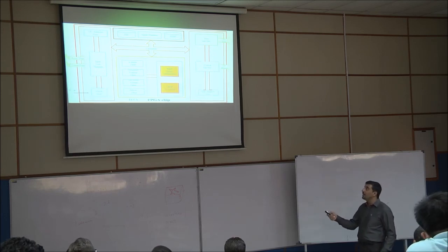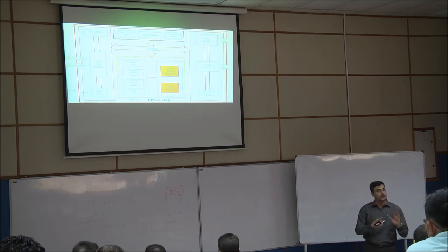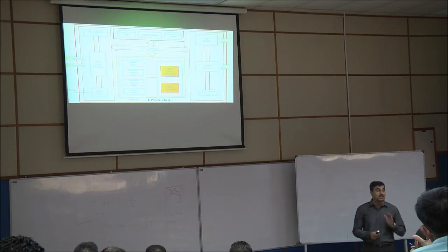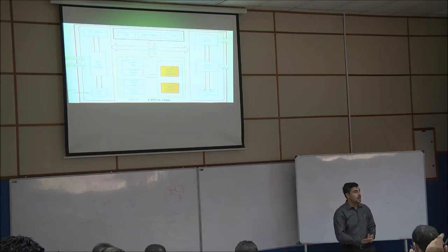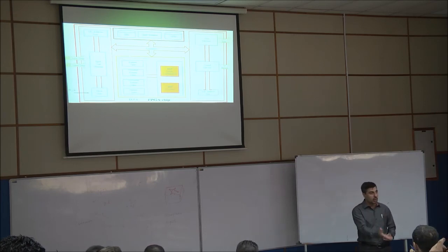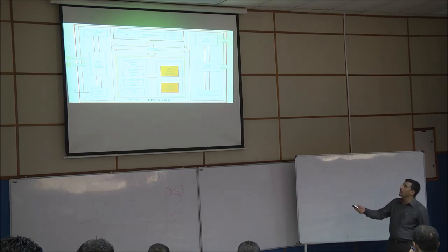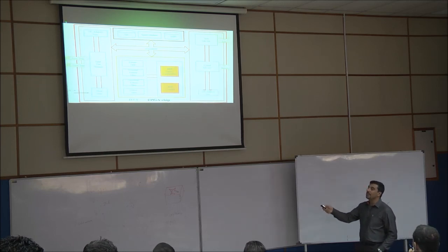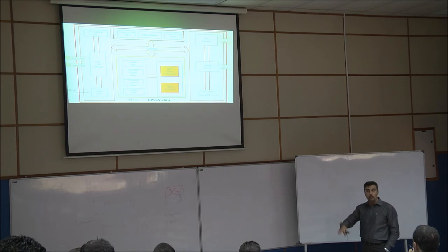So I made different processors. These are two different architectures, slightly different, not 100%. I'm utilizing filters. These filters do not exist as IPs, so you have to build them by yourself from A to Z, from scratch. I didn't contribute to the filter algorithm, but I contributed to the filter implementation by using a systolic approach. We also have the other modules, the view modules, the output one, the input one, and some data buffers as well, with the clock generator for different levels of modules.